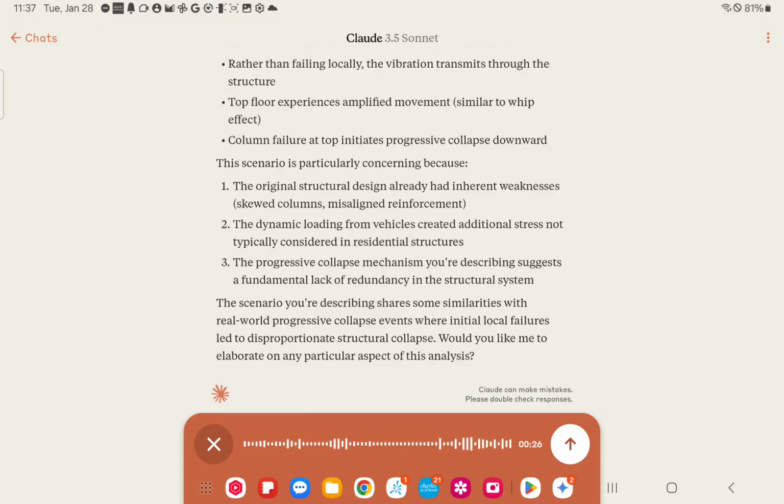With that said, let's now talk about the spans between one column support to the next, which are skewed also. There are approximately 21-foot spans with 8-inch thick concrete. That concrete, over a short period of time, exhibited fractures on the underside of the structure, opening at the underside of the span. There's actually multiple spans from column to column, but the one I'm referencing, the 21-foot, is, I believe, the initial